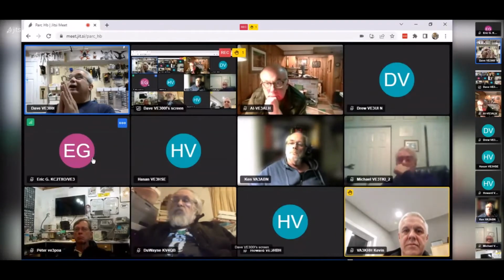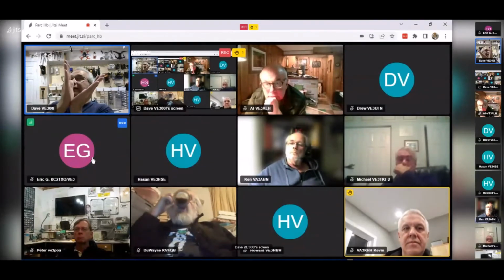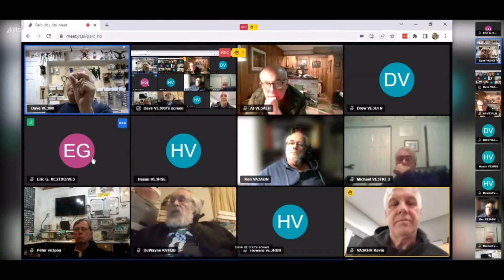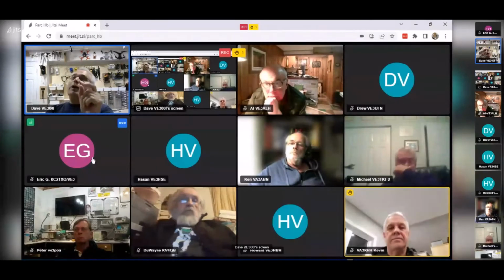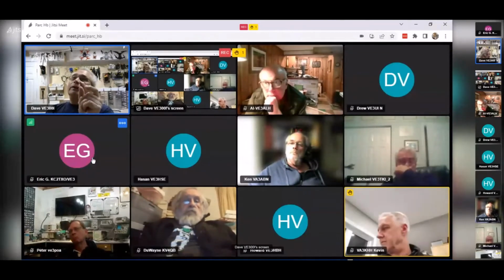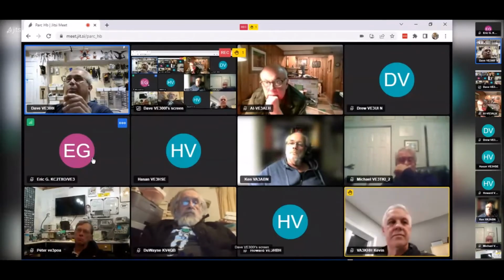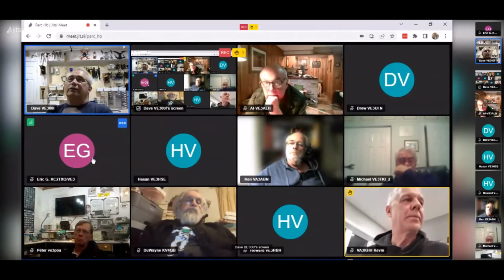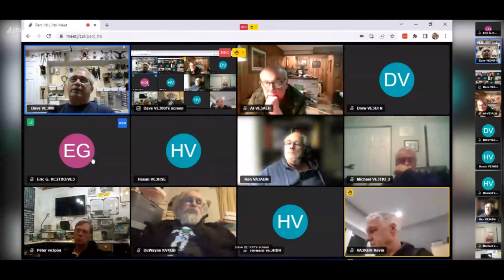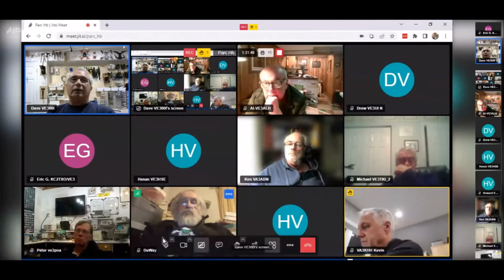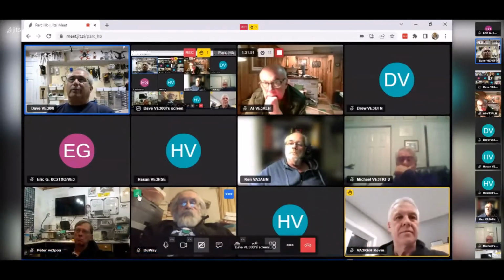So if you've got a big error in terms of how far the robot's leaning, you have to take that PID output and convert it into a smaller, narrower pulse width. It's a non-linear system. And I think Kevin put his hand up. I think Kevin could probably explain this a lot better than I could. Kevin.